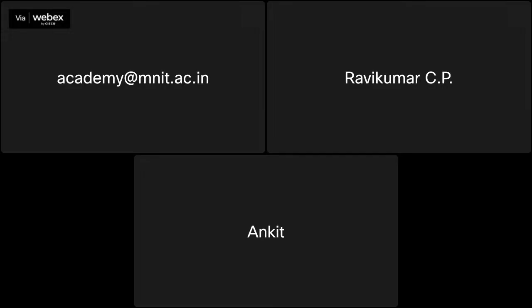And remember how we instantiate the subtractor. So subtractor 4-bit, which we wrote earlier, right? So this is our subtractor 4-bit, and we are creating an instance of it here. And the instance name we gave was sub4 instance. You can give any name you want.